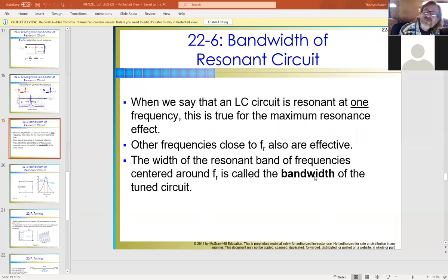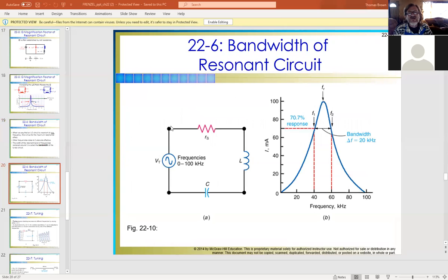Distortion being where the signal's not optimal, where you're getting some kind of frequency out, but it's all kind of wavery, so you wouldn't have a steady state signal. And these are not optimal effects, basically, okay? So this is what we mean when we talk about the bandwidth of the tuned circuit. The circuit works ideally for this, and anything else, not so much.